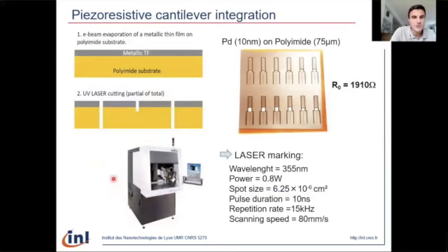Concerning the elaboration process of the piezoresistive cantilever, we have developed a very simple two-step process that is depicted here on this schematic. We have first integrated by e-beam evaporation a 10 nanometer thick palladium layer on top of a 75 micron thick polyimide substrate. Then we have used UV laser marking to pattern the cantilever geometry and also to pattern the piezoresistive elements and electrical pads for connection to the PCB.